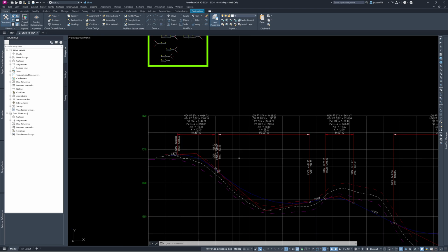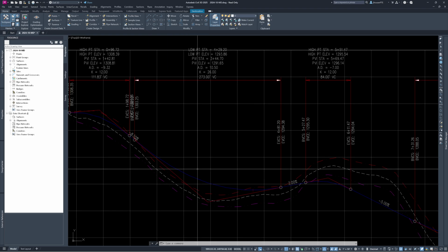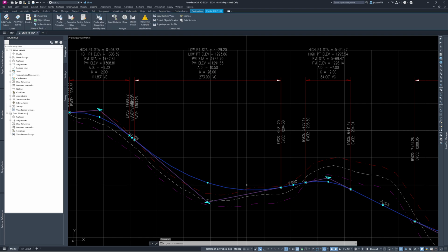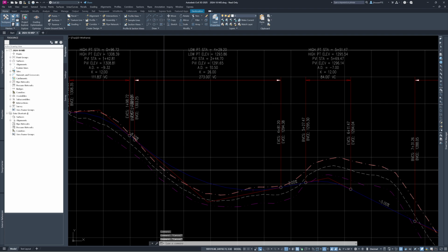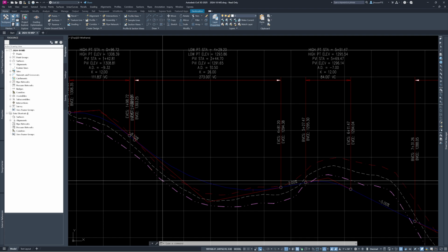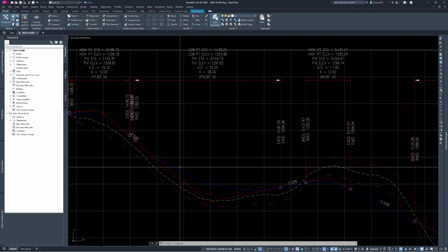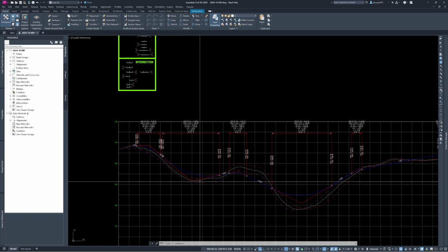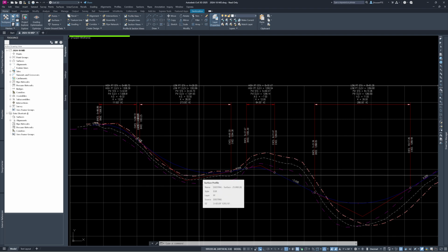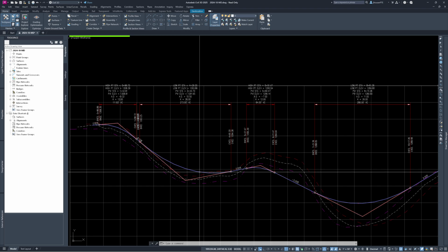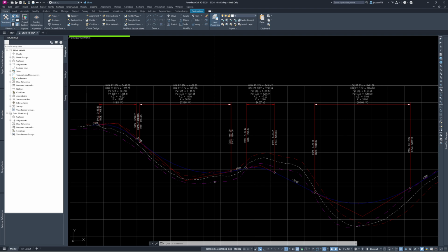All right. So like I said, we have a proposed centerline elevation on your profile. The white is the existing grade, the red is existing grade to the right, and the magenta is existing grade to the left. Now those offsets are set at 25. That is the width of our corridor in this right of way. Sometimes we would extend that out to the building setback line. Again, refer to last month's training if you need a refresher on how to set those up.